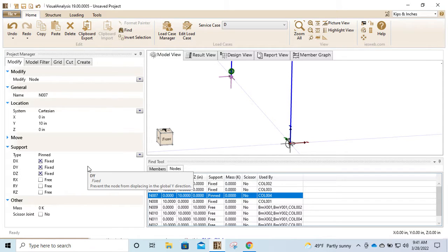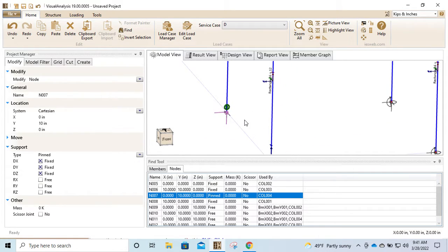Hopefully that makes sense. So if you just get rid of the circles on the member, then you're good on that connection. Like you can pin it. Yes, because then that node has some means of fixity between it and the element. So could you either pin the node and not release the member, or fix the node and release the member? Sure.